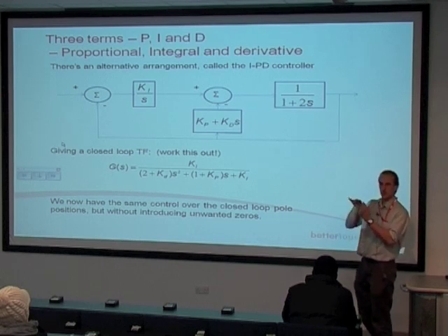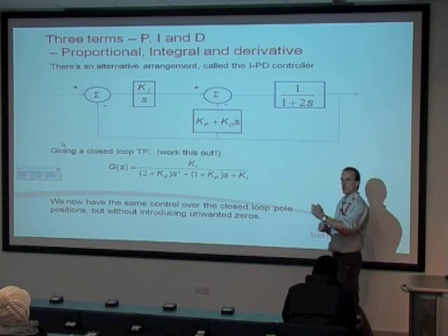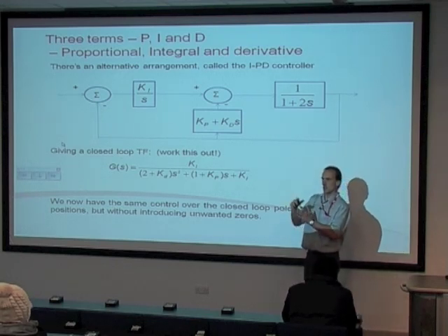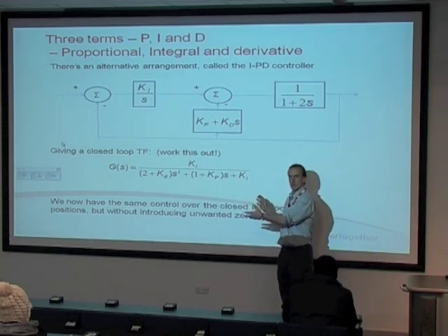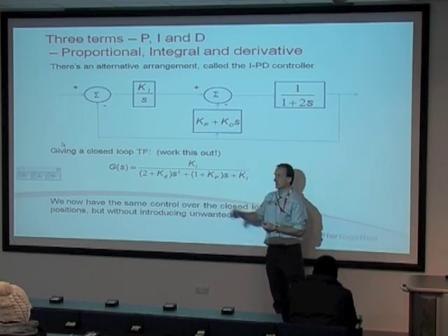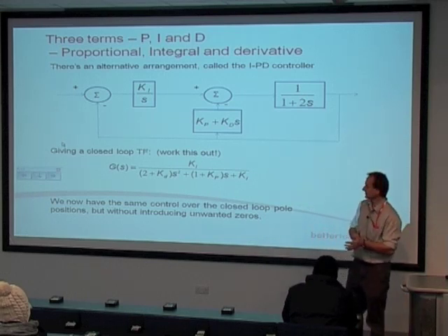When you've got it into just oscillation, and you've got a value for Kp, you turn that down by a certain fraction, you make Kd 0.6 of that one, and there are all these empirically derived formulae for working out the different Ks to give you a fairly standard performance.